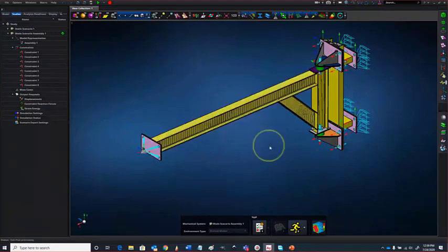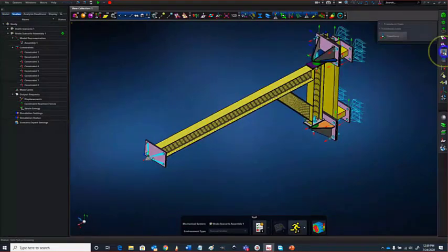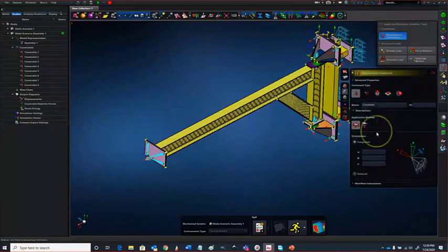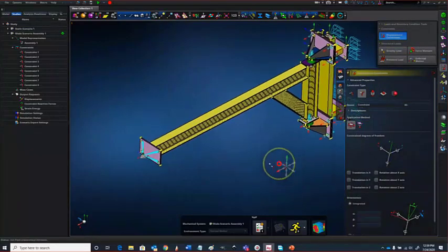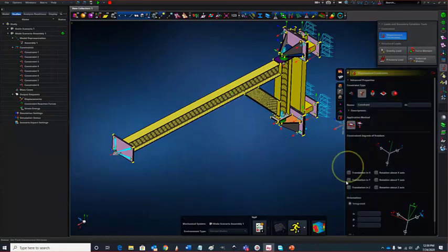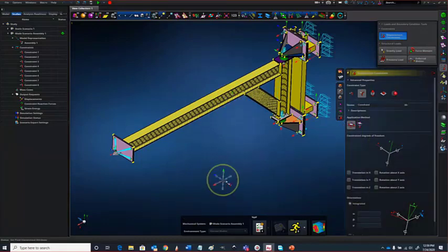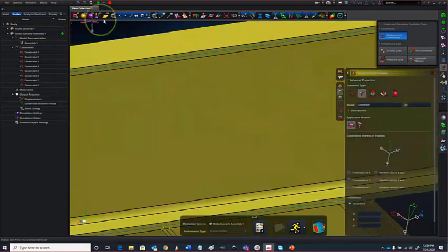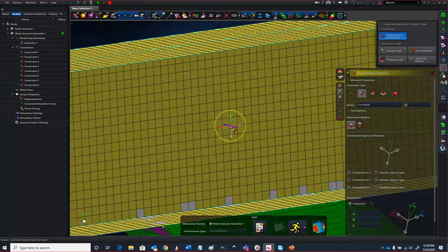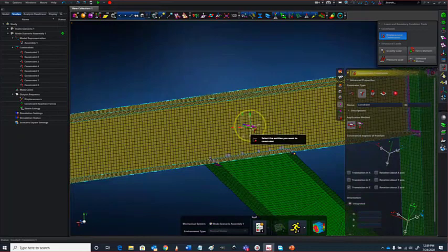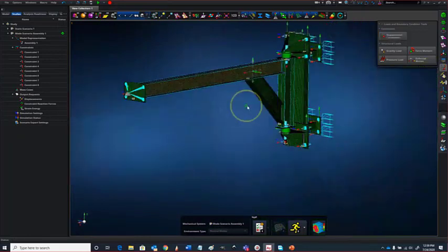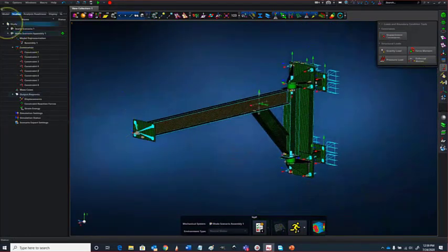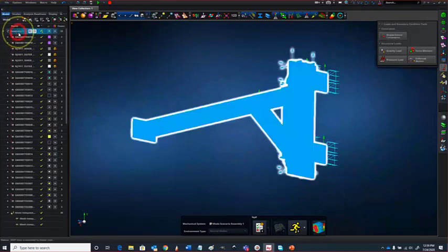We'll just have to put on the handbrake to eliminate that rigid body mode. So the real model has a lateral actuator or gas strut that locks it somewhere in this region in a lateral direction. So let's just put an arbitrary thing over there. So now the linear static analysis should be fine.